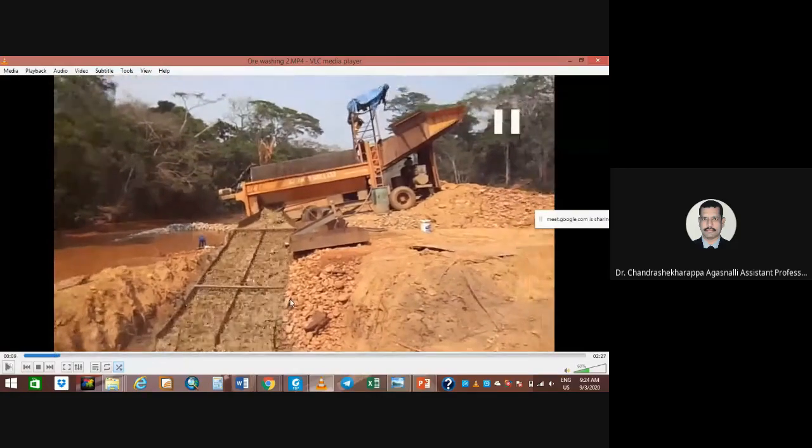Here this is a very short distance. Actually, it should be a longer one, and the flow should go very slowly. Otherwise, it cannot catch the heavier minerals. Say, for example, gold has a specific gravity, a bulk density, of 19.3. So here the gold is going to settle down at this place in the channel, and the rest of the sandy and clay materials are washed into the tailings. Oversized material is going out here.